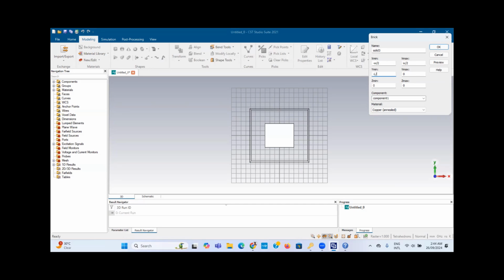I'm using these variables because it's easy to go for the parametric sweep or optimization with these variables. However, if you are going to use exact numbers, it's going to be very hard for you at the end when you have to change the parameters. For instance, I'm going to show you at the end. Sometimes you desire to operate some antenna at 25 gigahertz, but its operational band is not what you have designed for. So you have to go for parametric sweeps.